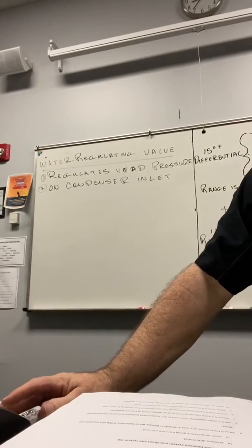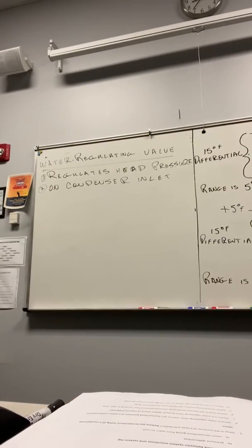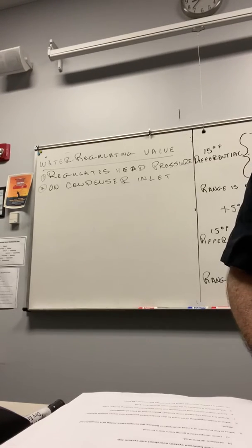So what happens is the valve takes a pressure reading from the high pressure side and controls the water in order to establish a predetermined pressure. It's controlled by two pressures, the high side and the spring that's in it. And if we flip back a page, I told you we'd go back to this real quick. Go to page, where were we? 353. First paragraph under picture 1436.